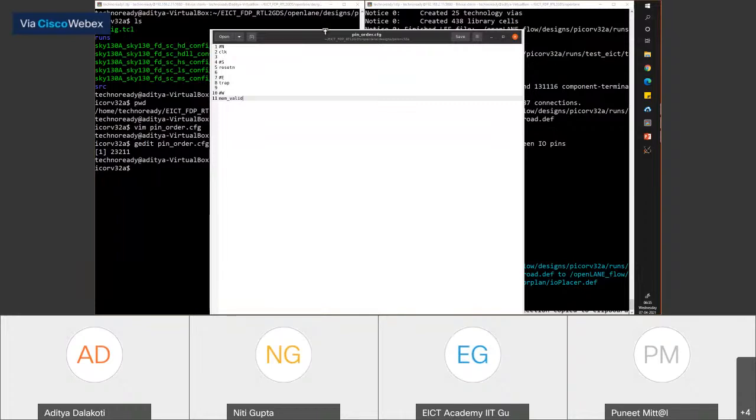Okay, Naveen has a good question. He's asking, how do we know the pin directions? How do we set them? Excellent question. Let's assume for a moment that you are creating a block inside a SOC. With respect to routing, what is the pin order you care about? That is how you create the pin order. It has to ease up your routing basically if it is a block.